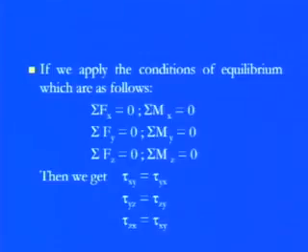So what we can do here is simply apply these symmetrical conditions to these equations, and we can reduce the 9 components. At every point, if we are calculating these 9 components, it is pretty tough to check the stress every time, because if the load application is changing, how these 9 components are changing, or which one is dominating and which one is not, is pretty tough.